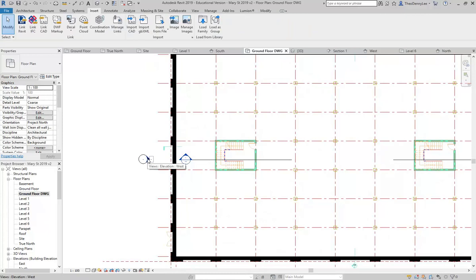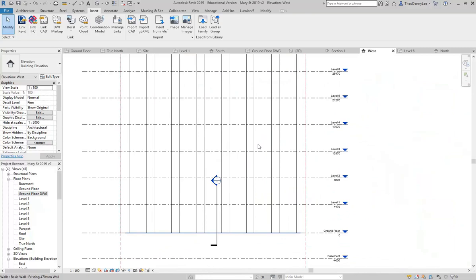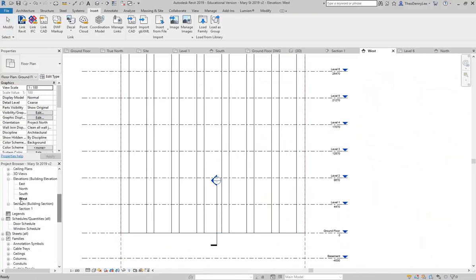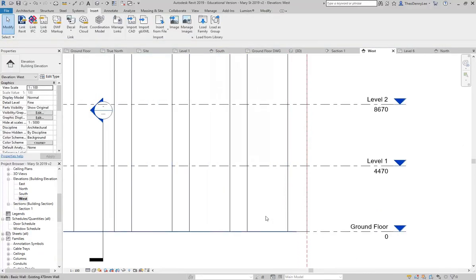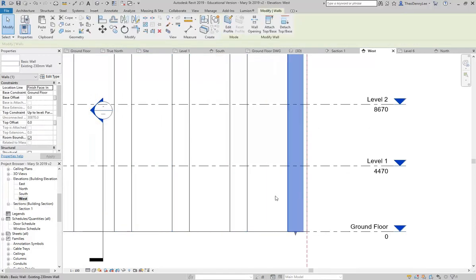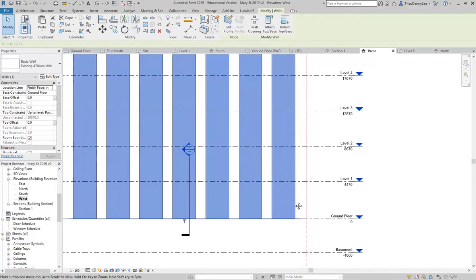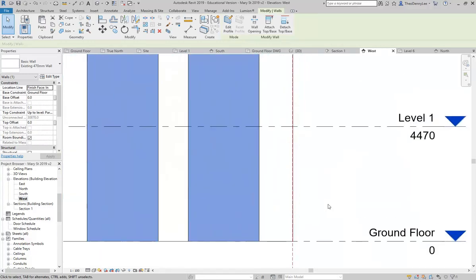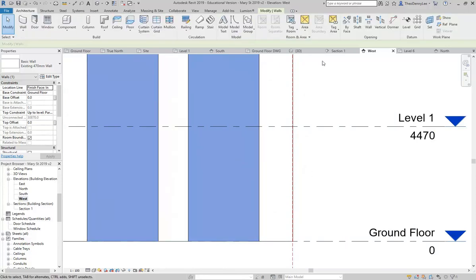This is my west elevation, that arrow. So if you double click on that arrowhead, it'll open the view. I could just go to west in the project browser. So then just have a go at selecting that wall, not the pier, but the main wall that goes all the way along the building. And then we've got to make an opening. So I don't want to confuse things too much, but I'm just seeing where you're at. Have you used any of these opening tools on the architecture tab? Like wall opening? No? Good, okay, so we'll leave those for now.